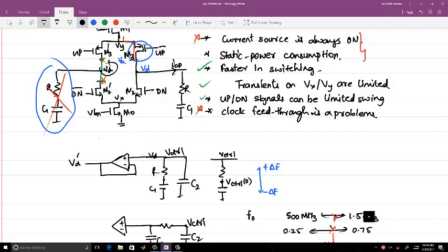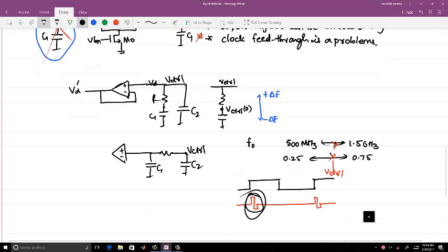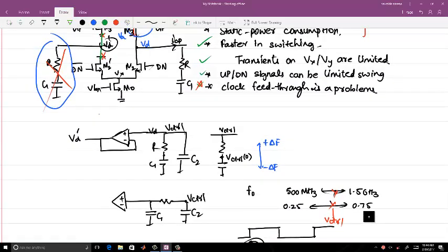But if you are doing any frequency modulation on the PLL, then this bandwidth of the loop will be a problem. So one other thing I can tell here is that the PLL is a sampled system with the reference frequency. In most of the cases, if you are changing the frequency of the PLL output or applying any phase change to the PLL output, you will be applying those changes at reference frequencies. Faster than reference frequency will not work here because this is sampled at FREF.